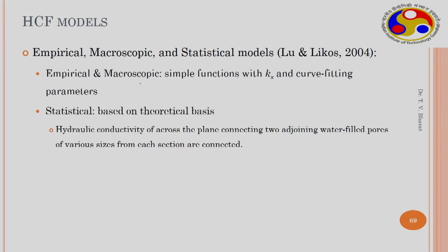They may use Ks in the expression and some curve fitting parameters. These are simple expressions like y equals mx plus b, such as linear expressions, that they use for the hydraulic conductivity functions. Or, using the macroscopic behavior, they may see the similarity between HCF and SWCC. Based on that, they utilize the similarity between these parameters to predict.